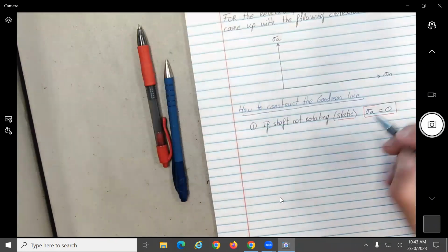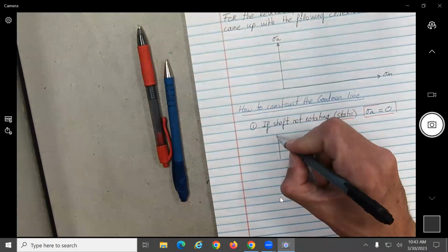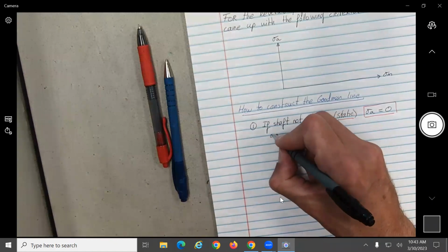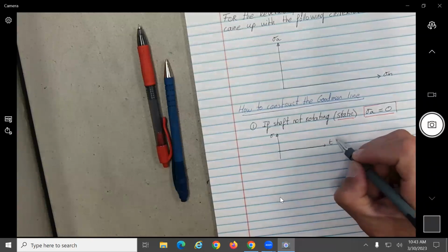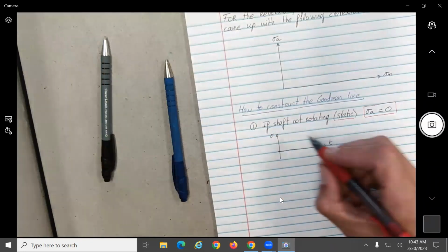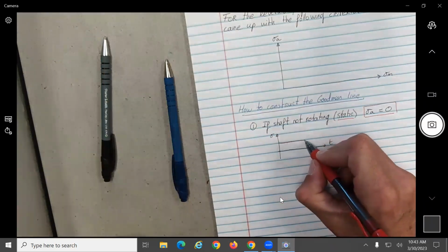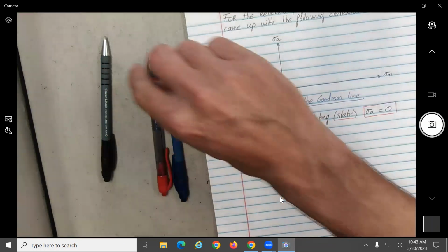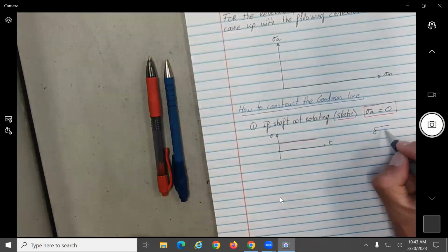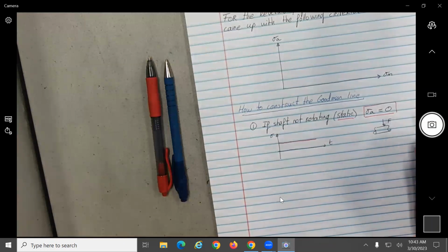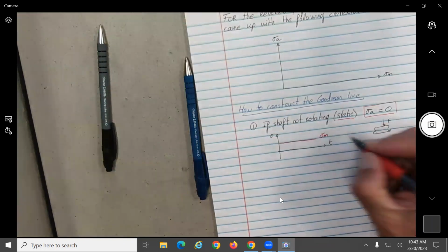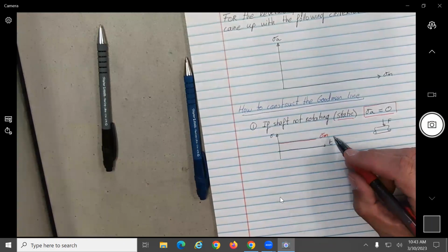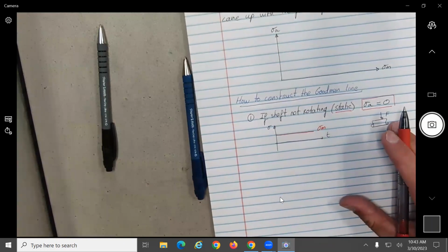So in other words, we have static loading. If you want to look at it, let me do figures, I like to do figures. This is the stress, this is the time. This is the figure that I did before. It's just one force being applied, okay? In that case, the stress will be constant and equal to the sigma sub m, the mid-range stress, due just to the static force.